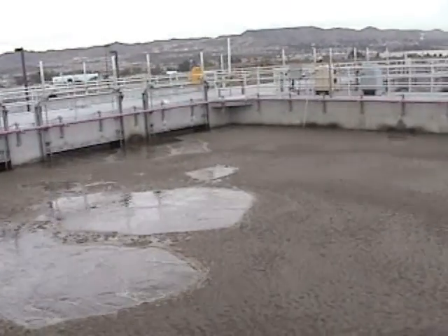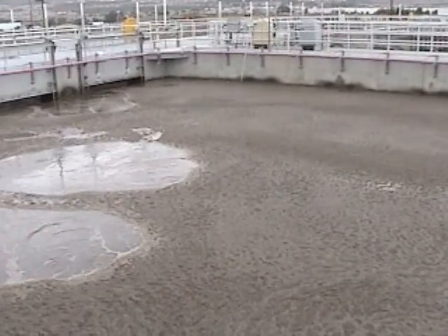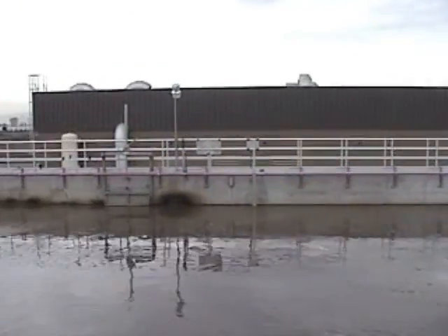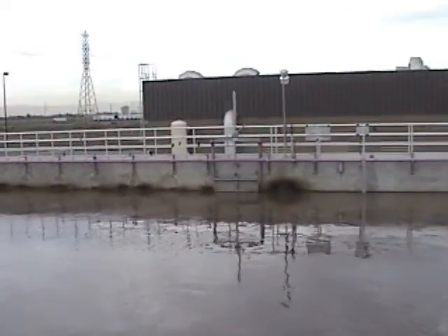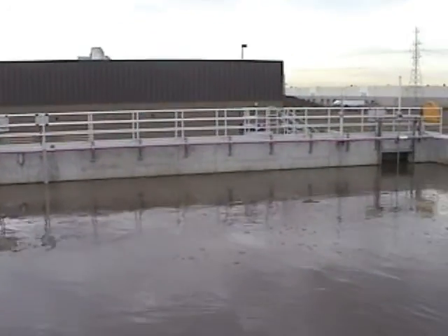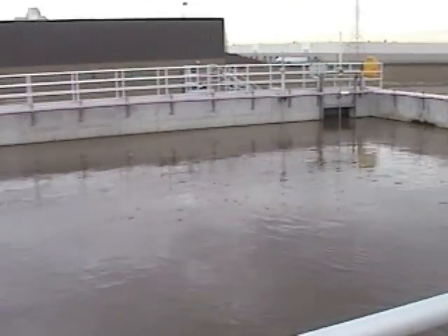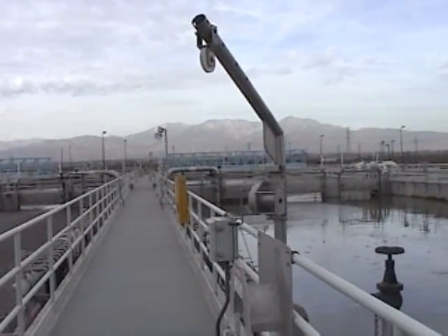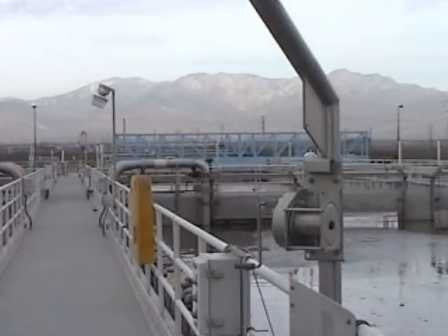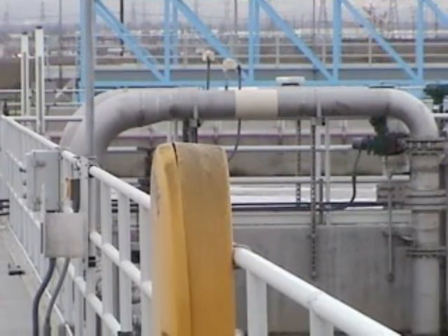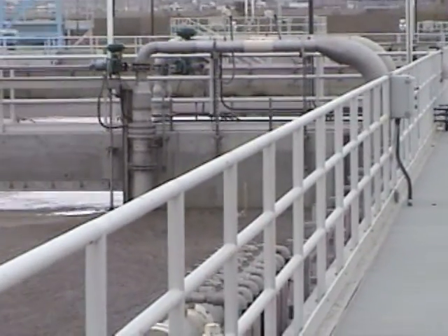Here, what we did is we raised the DO. What happened here was the blower was in manual, and it was pumping air into the system, but not enough. Although the valves were in auto, they were 100% open, and we just didn't have enough air flowing into these tanks. And then the Nocardia took hold and grew.